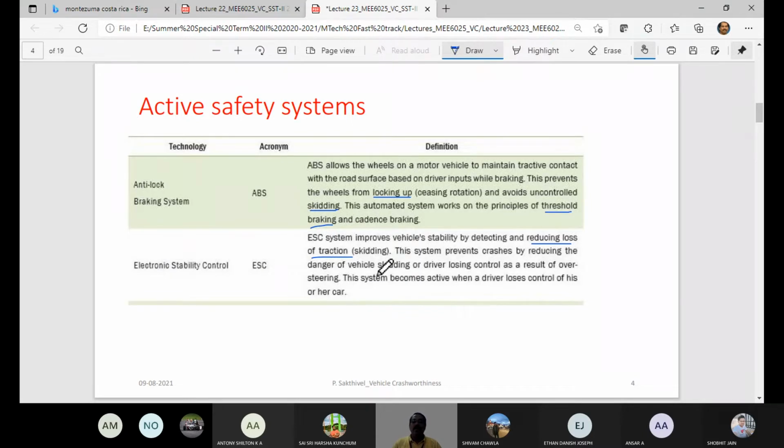We also have learned about what hydroplaning is. Hydroplaning is the complete lifting of your tire from the road surface because of a wedge of fluid that comes between the wheel and the road surface. In such a condition, you have hydraulic lift force, and that would create loss of contact of the tire with the road, and that should be prevented.